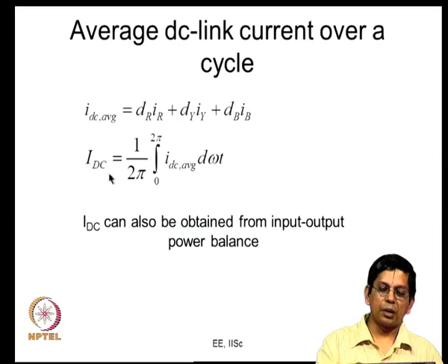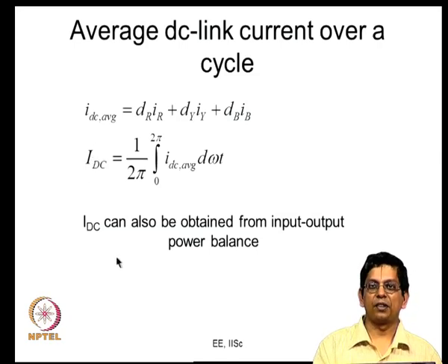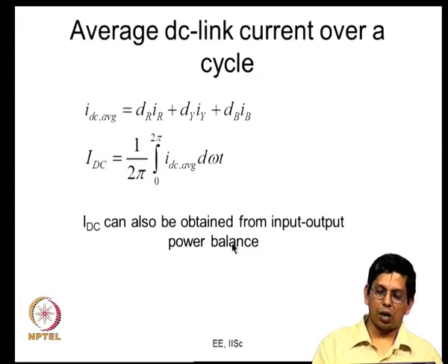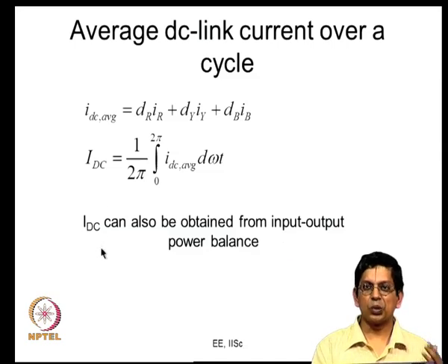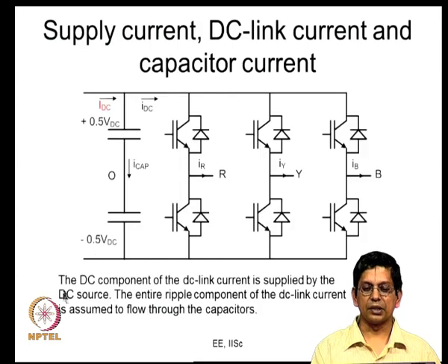So, IDC can be expressed as the AC side power divided by whatever is your VDC. The AC side power is available from the DC bus voltage, modulation index, the load current amplitude and the load power factor angle. So, that is also done, which is something we discussed towards the end, and I had left it as an exercise for you in the last exercise.